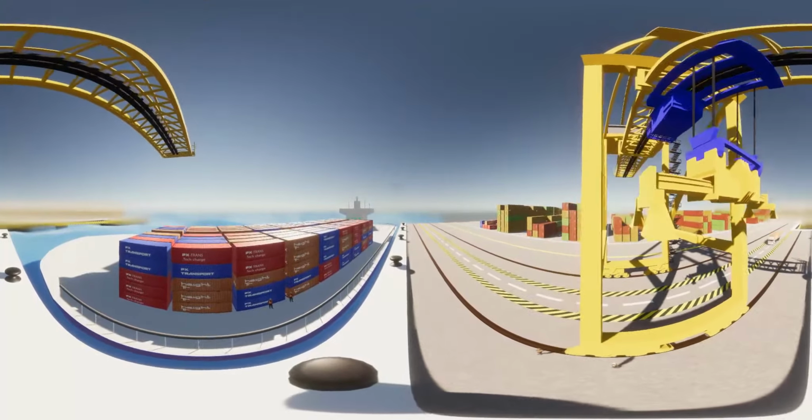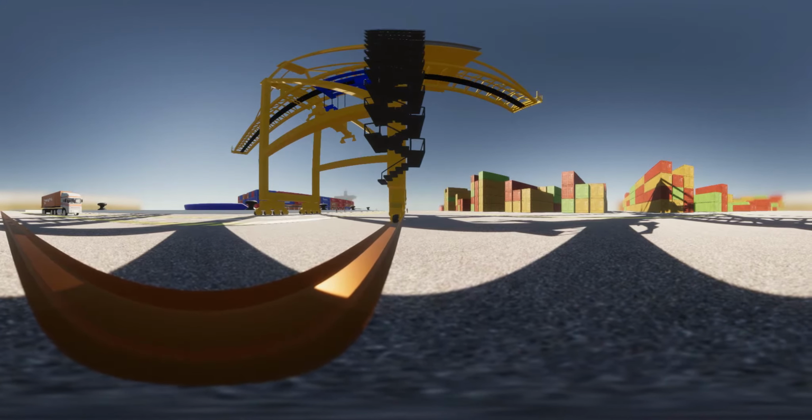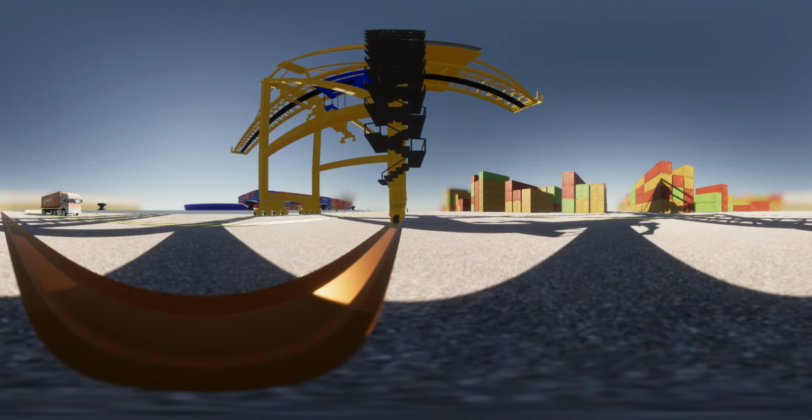The spreader must be at a safe height whilst traveling. Spreader swing must be eliminated at the end of travel. Ensure that there are no obstacles on the gantry path before traveling. In case of emergency, make use of the e-stop to stop the QC.